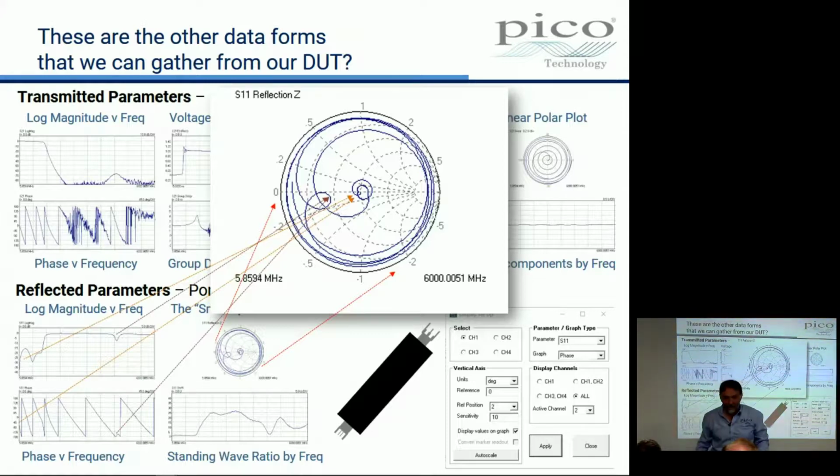It's a polar plot of S11. Well, not quite, but we'll come to that. But essentially, it's the same as that over there. But it's got a grid on it, which is the Smith grid. And we'll talk about the Smith grid in the next talk. So here we go. We can do the same thing as we did last time. We've got S11 magnitude here, and this is log magnitude, and we've got S11 phase here, yeah?